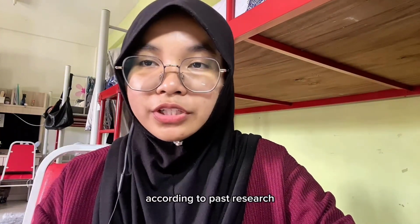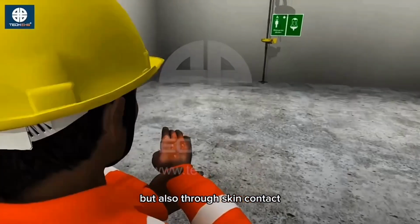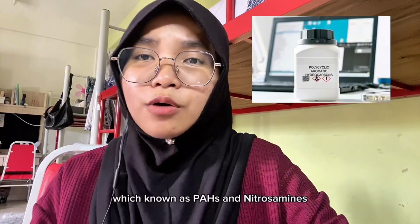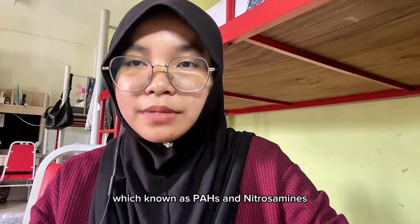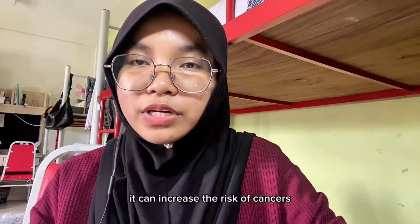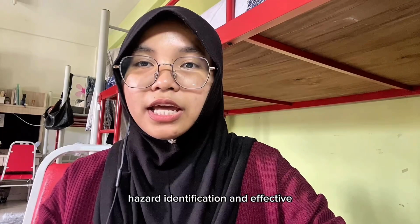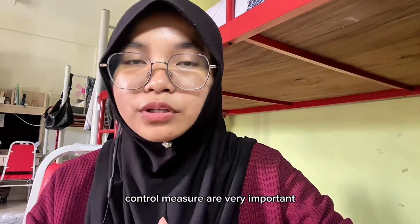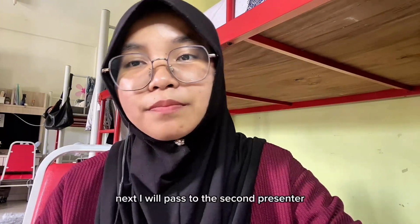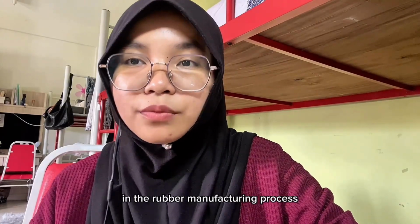According to past research, workers are exposed not only through inhalation of dust and fumes, but also through skin contact with harmful chemicals such as polycyclic aromatic hydrocarbons, known as PAHs, and nitrosamines. These substances can cause dermatitis, and in the long term, they can increase the risk of cancers. Because of this, hazard identification and effective control measures are very important to protect workers and reduce occupational disease. Next, I will pass to the second presenter to discuss the hazards identified in the rubber manufacturing process.